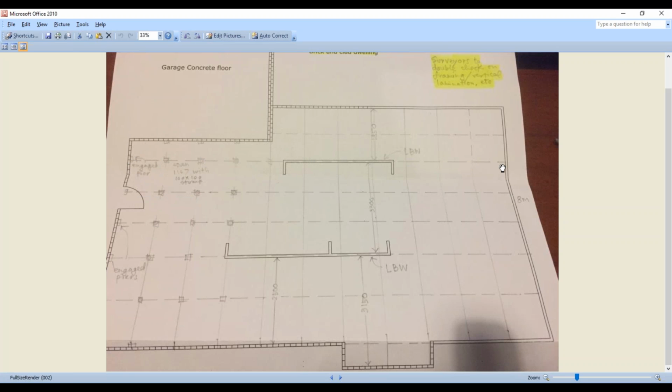As I said, by all means, that's not wrong, but you can start to see, once we start over-engineering it a little bit, the extra costs that might start to have on the project. So if Subit's got how many rows of bearers? 1, 2, 3, 4, 5, 6, 7, 8. He's got 8 rows of bearers, and then he's got 2 extra stumps on each row. So realistically, Subit's plan compared to mine, he's going to have 16 extra stumps in there. That's 16 extra holes drilled by the auger, then 16 extra concrete stumps, and all that concrete to go with it.